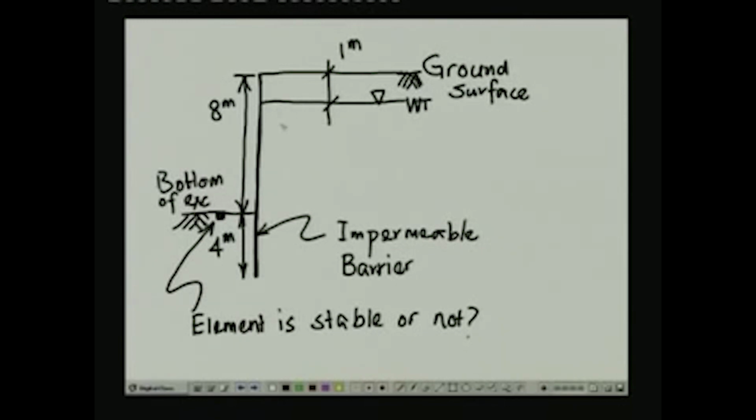In this particular situation, the groundwater table inside the excavation was near the bottom of the excavation, as I indicated in the question statement. Because the groundwater table on the outside of the excavation is at a greater elevation than the groundwater table inside the excavation, the groundwater is going to move downward around the impermeable barrier and into the excavation.